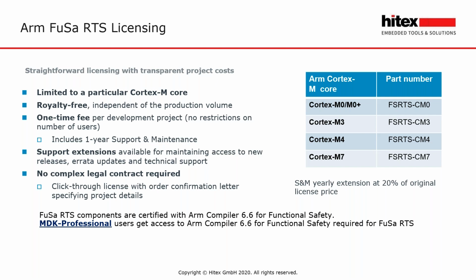But again, the one thing that I would emphasize is that you do need to use it in conjunction with the MDK Professional. This has the certified version of the compiler, and the two sit together. You can't use the functional safety library with a different compiler. Its certification then won't be valid.